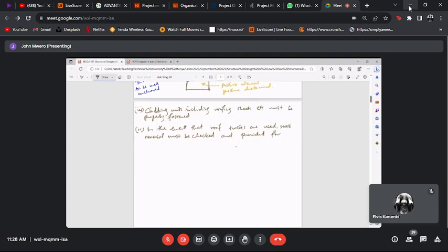So when you have a roof structure that is made of trusses, say something like that, you find that under gravity loads, for truss analysis, if you can remember from the assumptions for trusses, is that trusses do not carry bending forces, so they're only loaded at the nodes because they only carry axial forces, that is tension and compression.